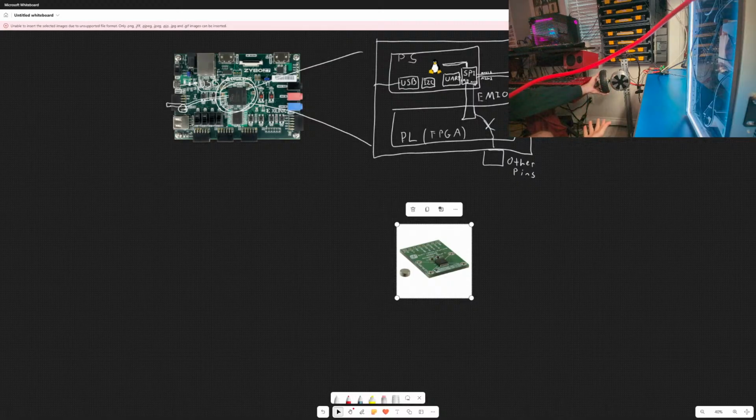But there's other types of encoder technologies out there called incremental encoders, which means that you have to home the motors first to get some semblance of where you are. And then the encoders are basically relative. So once you home it, you'll know where it is, and then you can start counting with the increments of the encoder from there. But, you know, that's not cool.